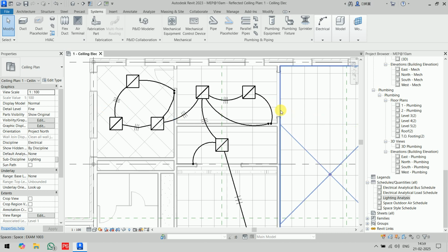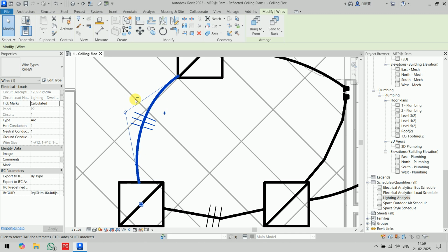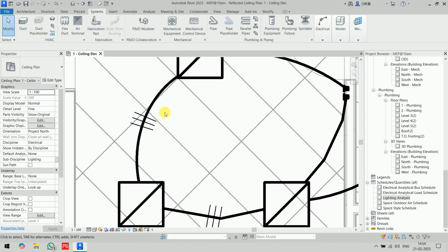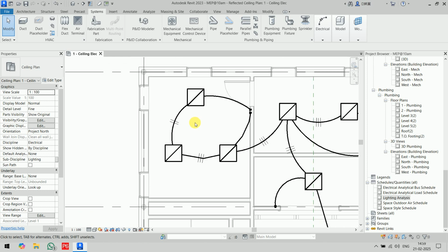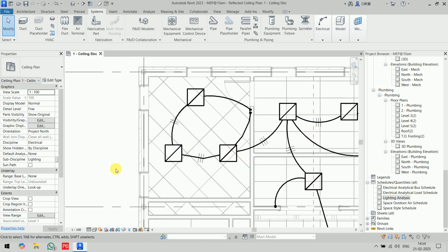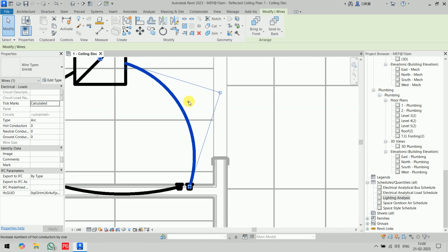So anything you require, you can draw the wiring manually, or you can connect the power connection into a wire, or even if you can select the number of wires, you can set a negative or positive number of wirings. That means 4 wires are in between these. This means 2 wires are in between these. Accordingly you can define. But this wires from panel to light can be drawn by us. Yes, you can draw, but this is manual. This is for automatic. It's not an automatic method. Like in here you will find this is a wire, there is a plus option. You can also define it manually, not an issue.